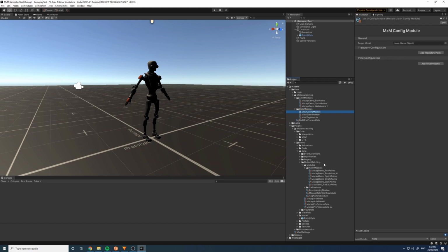With the config module, I'll grab the robot Kyle model, and we can add trajectory points. I'm going to add 5. Negative 0.666 is usually how I split them up in even intervals, and 1, because I want 1 second in the future and I want the rest to be even. So 2 past trajectory points with the negative, and 3 future trajectory points.